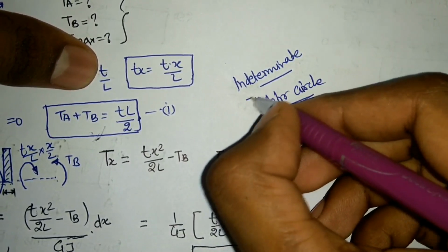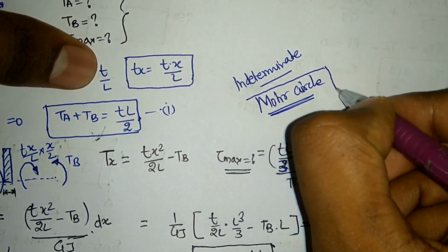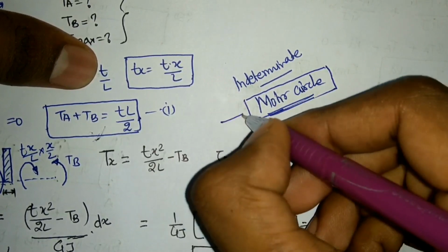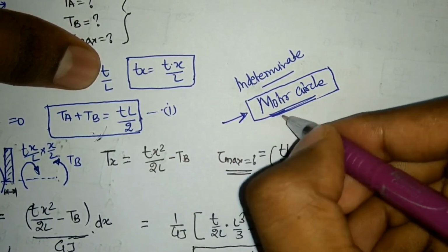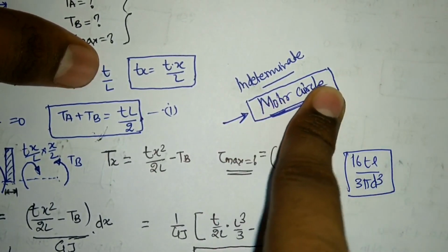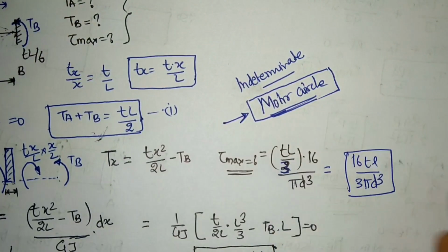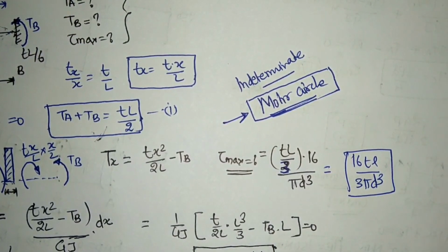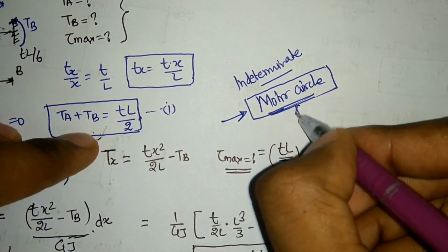and I will be explaining the derivation of all the formulas based upon Mohr circle. So basically, if you understand how to use a Mohr circle, you will be able to write all of the formulas related to principal stress, maximum shear stress, plane of maximum shear stress, plane of maximum principal stress, plane of zero shear, plane of anything, once you understand the Mohr circle.